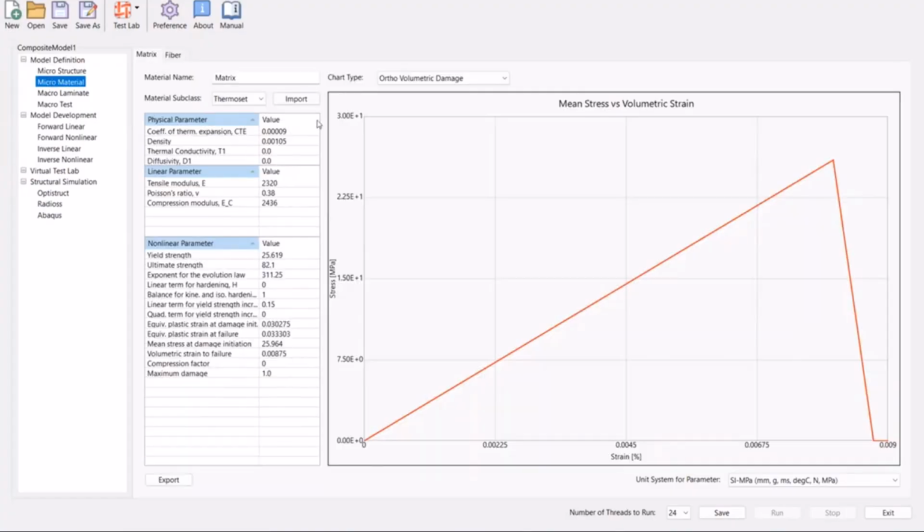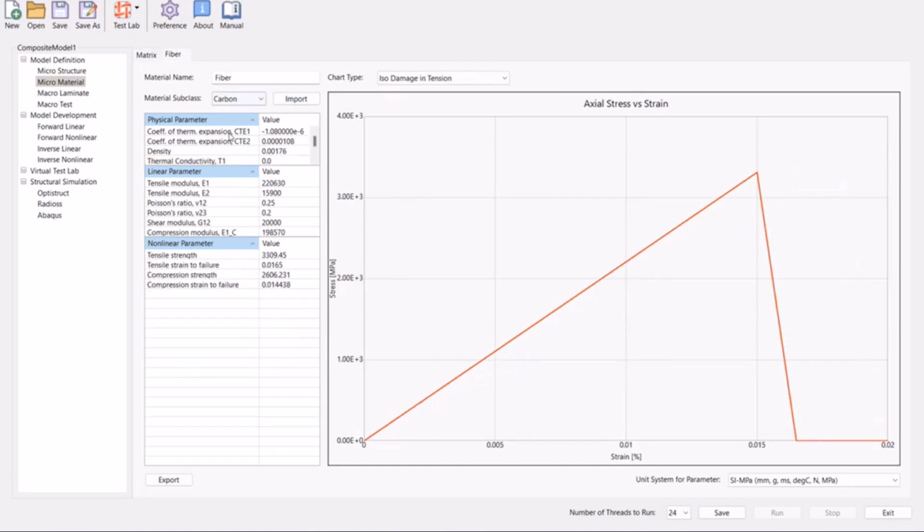As you can see, you can define the thermal conductivity. Let's put that value to 0.1 for the matrix and allow a bit more thermal conductivity, for example, from the fiber in one direction and less in the second direction. These values don't necessarily need to make sense.